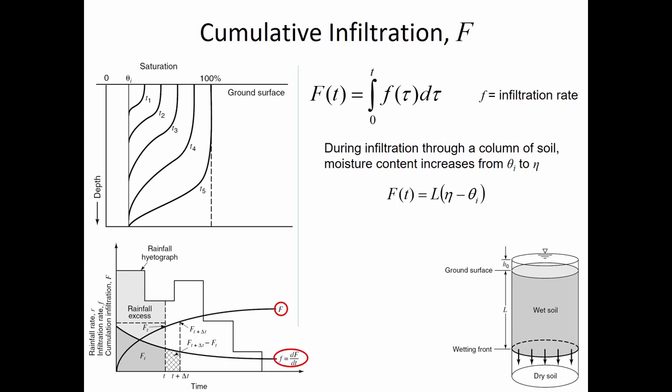So the physical length of this soil, like if the wetting front goes 10 centimeters, it's not that it was 10 centimeters of actual water that was infiltrated, because remember, some of this depth is occupied by solids, and there was some water there to begin with. So a 10 centimeter L does not mean that there was 10 centimeters of rainfall. 1 centimeter of rainfall may cause L to be 3 centimeters, or even more if there was a pretty high moisture content to begin with.